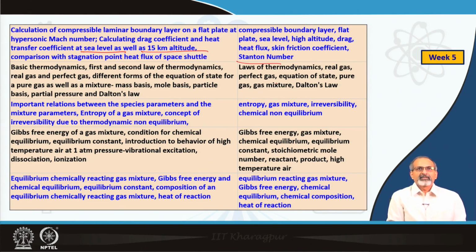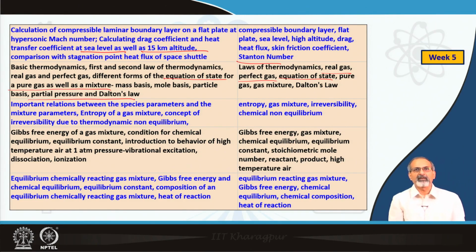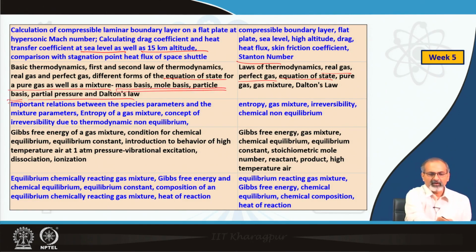the basic thermodynamics was again recapitulated both for real gas and perfect gas. We looked at the equation of state, and then we started discussing the equation of state for a pure gas as well as gas mixture. Whenever it comes to the gas mixture, of course, we introduce the partial pressure and Dalton's law. Not only that, we also looked at the equation of state under different bases like mass basis, mole basis, particle basis, which was subsequently used time and again in the remaining weeks of the course numerous times.